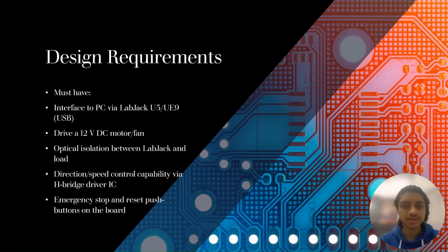Next slide, which is design requirements. The mandatory requirements were to interface the system to a PC using LabJack U3 or UE9, control a 12 volt DC fan, and provide optical isolation to protect the LabJack. We also use an H-bridge driver for the motor and include the emergency stop button and the reset button as well. So these were the core targets of our design which needed to be met.